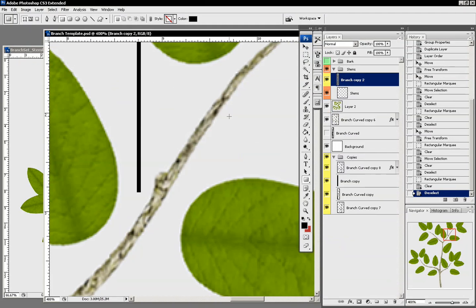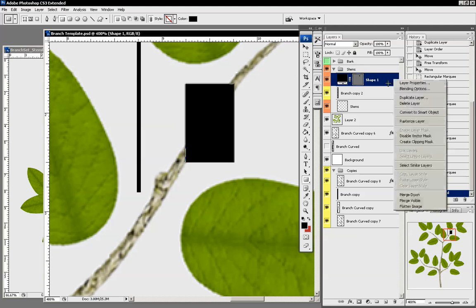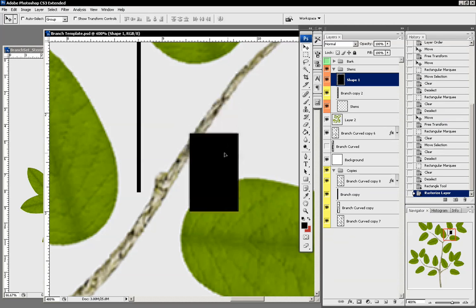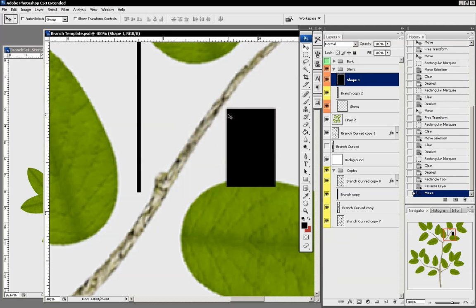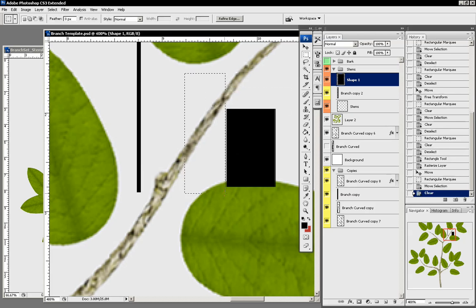I'm just going to create a basic box right now and rasterize it. Now, because we are zoomed into the image, if you take a look on the edges of the box, you're seeing it's not perfect, and we have it fading into gray. So what we'd have to do is go in with the marquee tool and delete those edges. So that can happen when you're creating shapes in Photoshop.